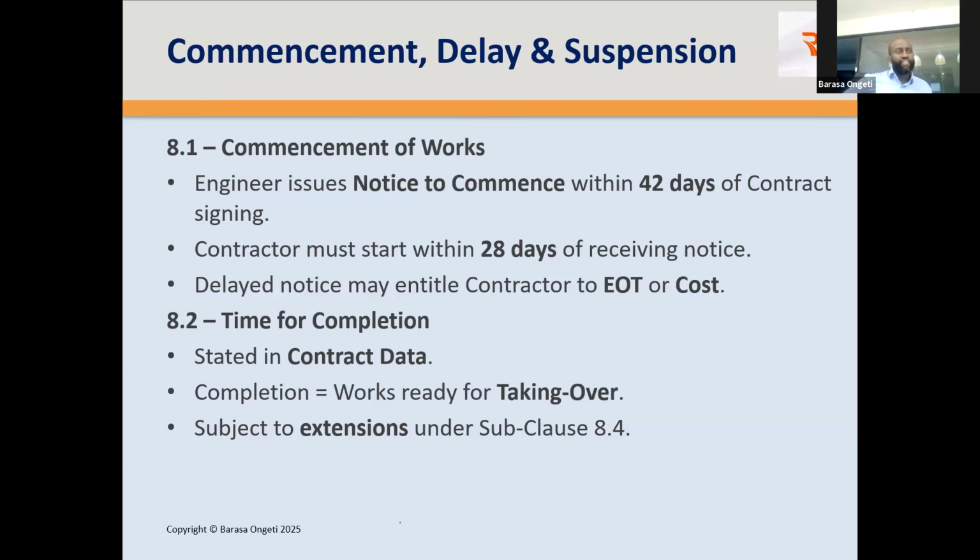Actually, FIDIC says, well, I've said 28 days here. FIDIC says reasonably practicable. So I believe I should change that. The contractor must start within a reasonably practical period after receiving the notice to commence, okay? Not 28 days. That's quite misleading. I don't know where I got that from. FIDIC says the contractor shall commence within a reasonably practical period after the commencement date, okay? Now, if the notice delays for one reason or another, the contractor may be entitled to extension of time